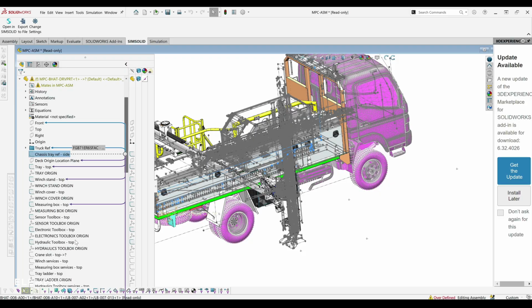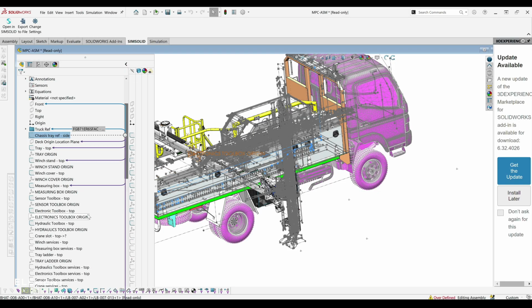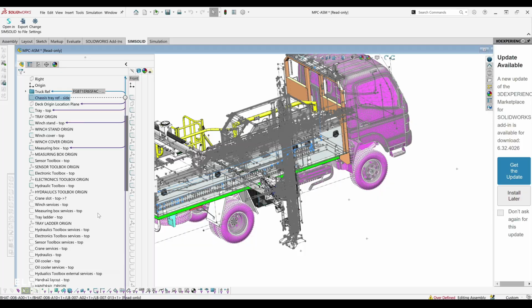If you were to have a feature referencing another feature, that is going to change. That edge or that vertex or that feature changes. We've found over the years that it basically crashes the model, and you can have a lot of issues. So sketches built on other sketches, put into a driving part, is the way that we have been successful in doing our CAD, and that's what we've seen from other clients and customers when they're doing good CAD as well. Yeah, so for the most part, this is the method we use.